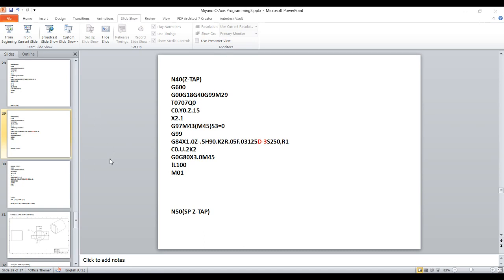That's the difference. Another difference on the Mitsubishi, the X-axis is not diameter anymore. It's a radial value, so it's just like your milling program, machining center program, you can import it and pretty much run it. You don't have to double up on your X dimension.